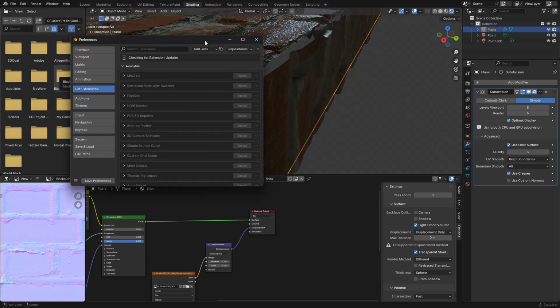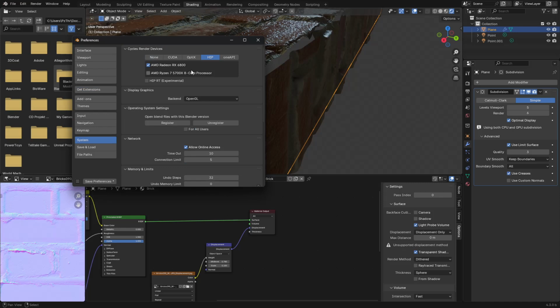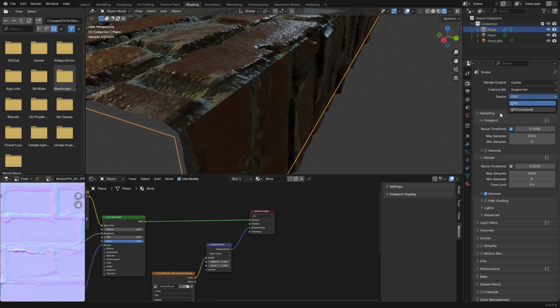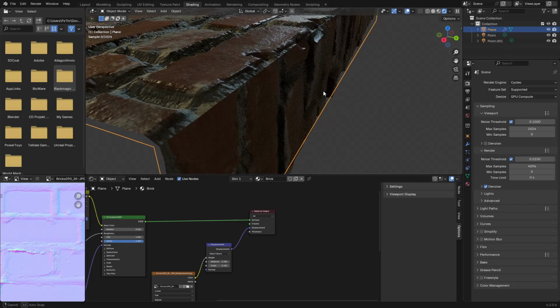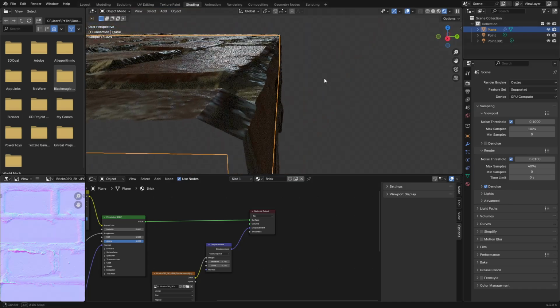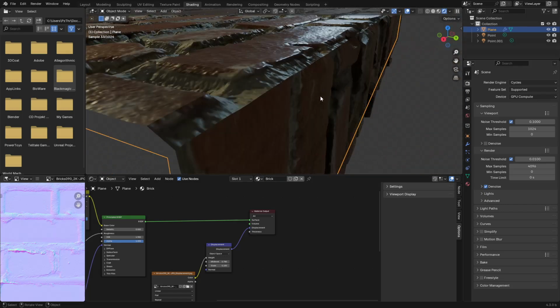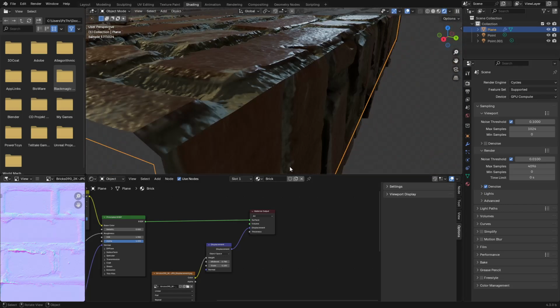So let me go ahead and switch my system to render on GPU real quick. Go to Cycles, set it to GPU. All right, and you see when it does this, there's no problem here now. With Cycles, for whatever reason, the Eevee displacement does that. That doesn't mean it's not useful. It's just not working the same as Cycles right now. It can still be used very well on terrains and things like that, where you have one big UV island more or less.